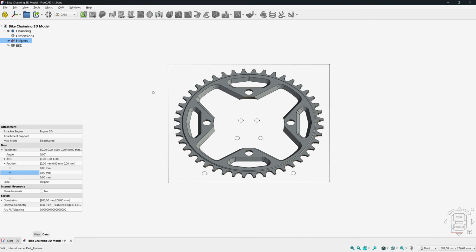Since we'll be machining aluminum, we need to pay attention to the different tool speeds as well as the milling depth. We also need to tell FreeCAD how to generate the code so that it can be correctly interpreted by our CNC. It can be a bit intimidating at first, but I'll guide you and you'll see that it's easily manageable. The first step is to create a job. To do this, click on this icon.